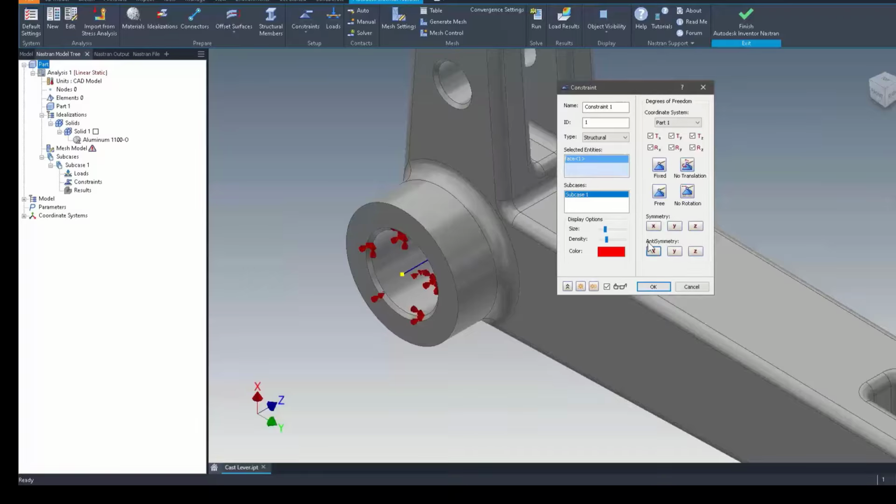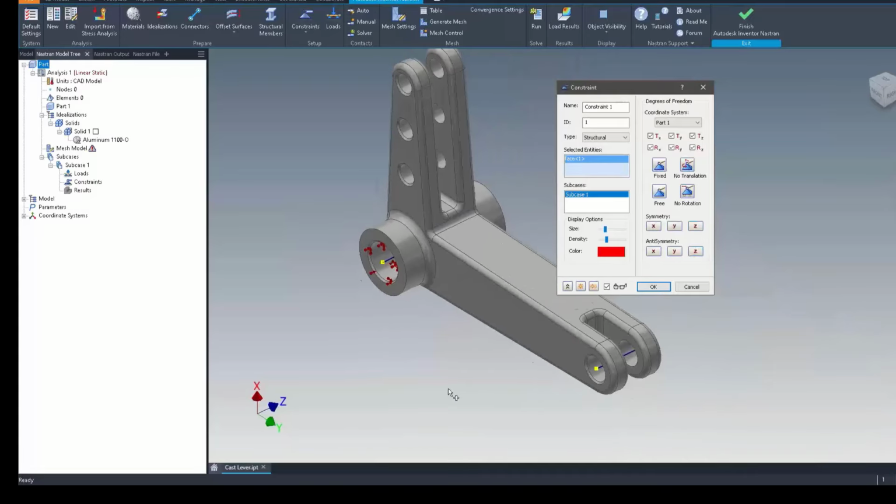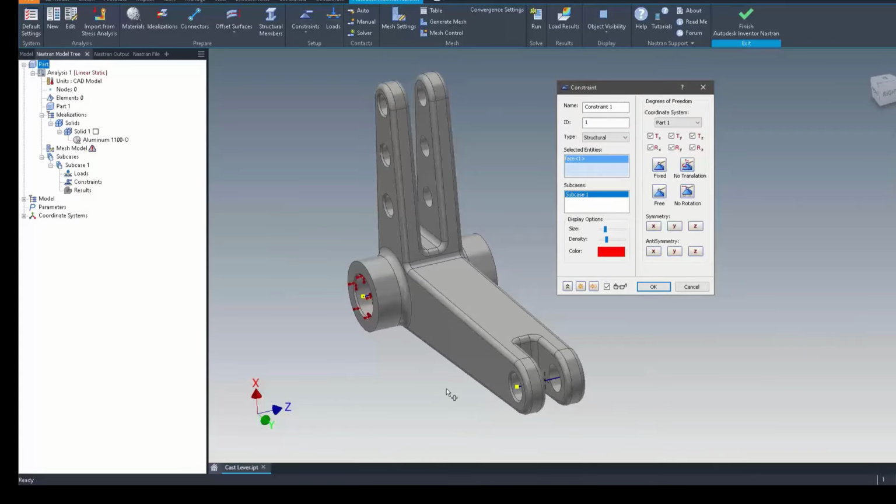get into next. You can also work with symmetry conditions. With symmetry, it can simplify on a very complex model. It can simplify the math, and the analysis time can be shortened down. If it is a symmetric model and it is encountering forces and constraints symmetrically, then analyzing one half of it will be a good indicator of what's going on in the overall.